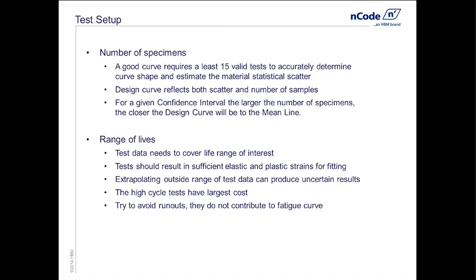Thing we never want to do with these curves: we're fitting this curve through test data, and extrapolation is very unpredictable. The curve has been defined by the test data. Areas outside the test region basically have no control. And so we want to ensure that we're never extrapolating from that curve. We'll see that in just a second.